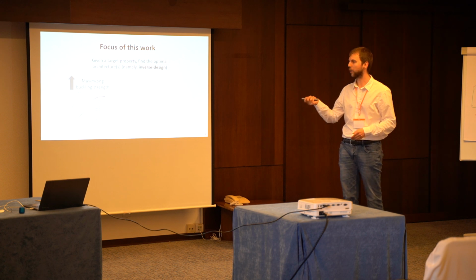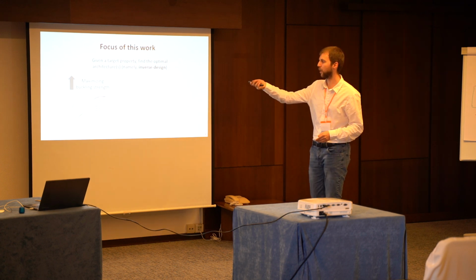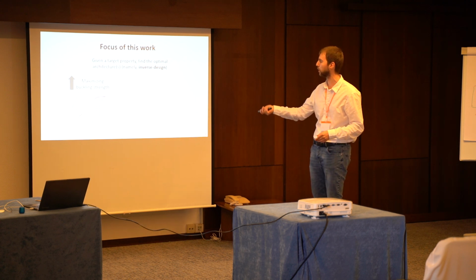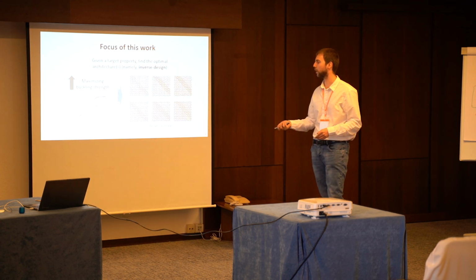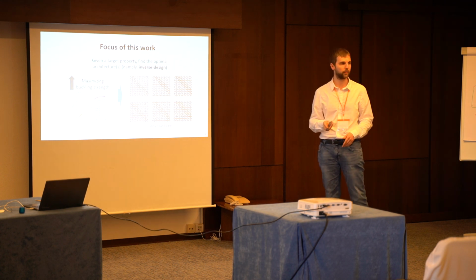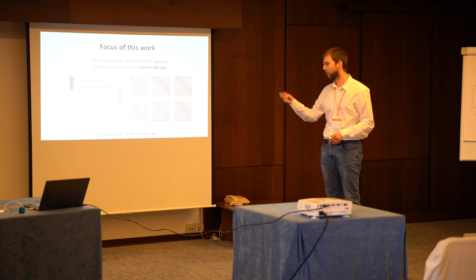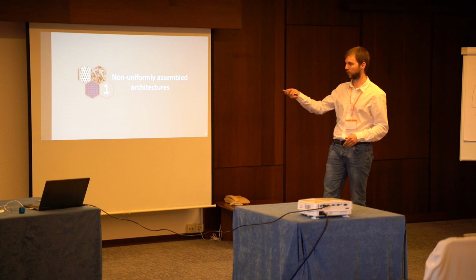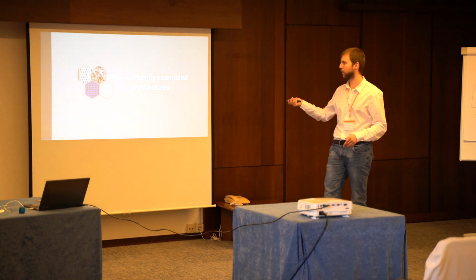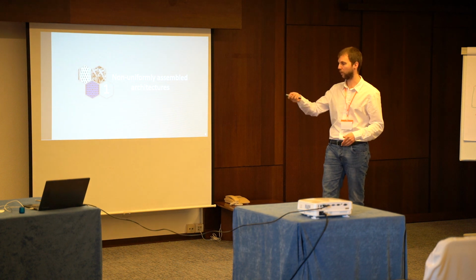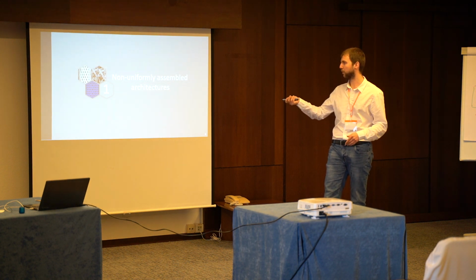In this case, we want to maximize buckling strength, defined as the maximum of the macroscopic effective stress-strain curves. And we obtain some design candidates, which will be later simulated and tested. This is the reason we are talking about inverse design of lattice materials. The first part is about non-uniformly assembled architectures. Despite the fancy name, now I'm showing you what it is about.